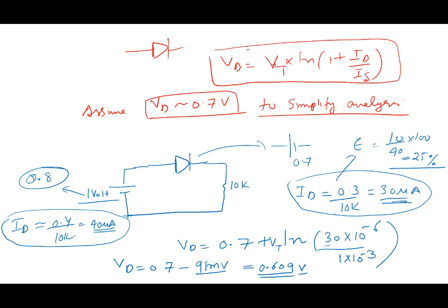The 0.7 volt model will give you an even huge error, very high error. So the model is breaking down. The model where you are replacing the diode by 0.7 volt is breaking down. It's already broken down. In fact, if you want to see complete breakdown of the model, then you take this circuit. Let's say I put some 100K or something.